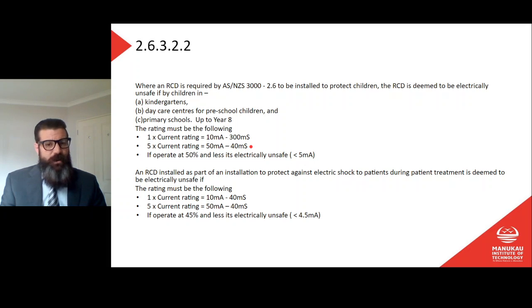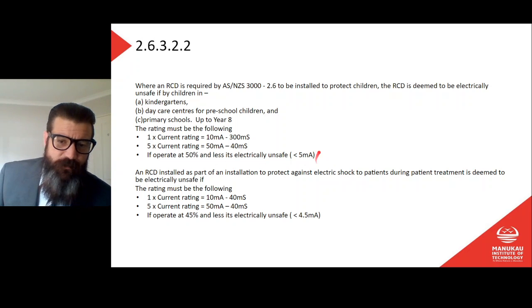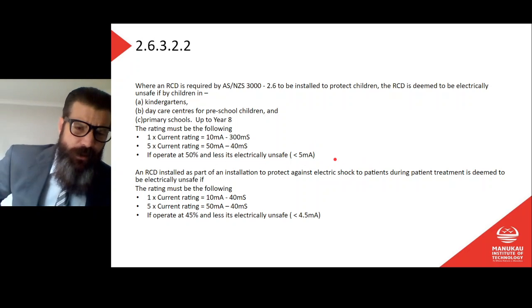1 times current rating, 10 milliamps, 300 millisecond tripping. 5 times current rating, 50 milliamps, 40 milliseconds tripping time. If operated at 50% and less, it's electrically unsafe, less than 5 milliamps. Okay, that's a confusingly worded sentence.